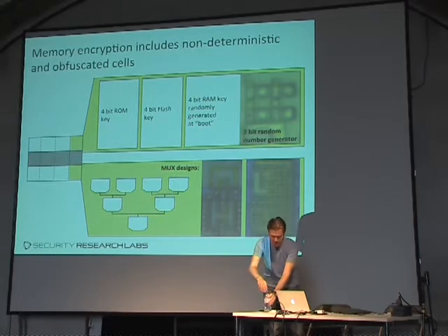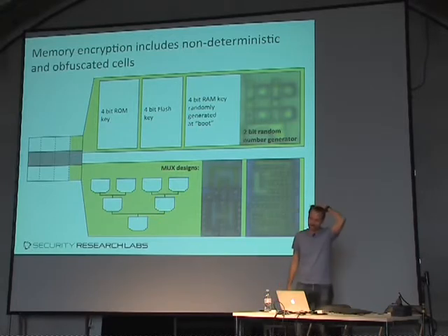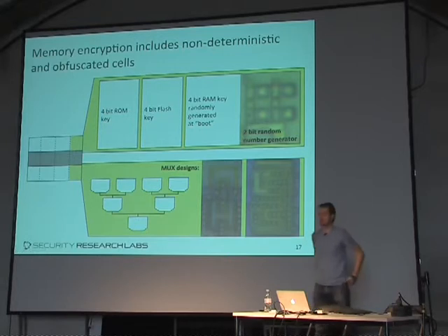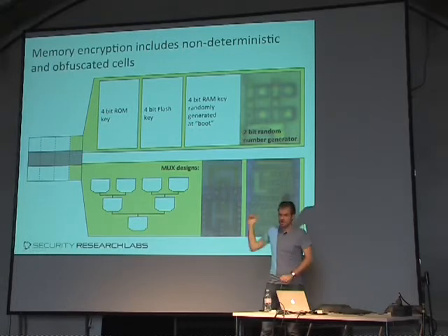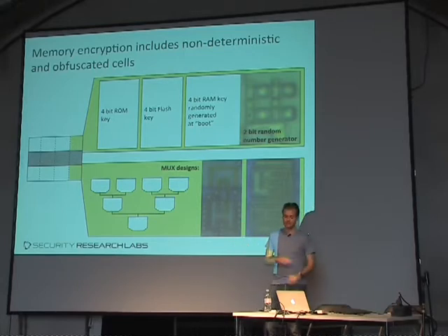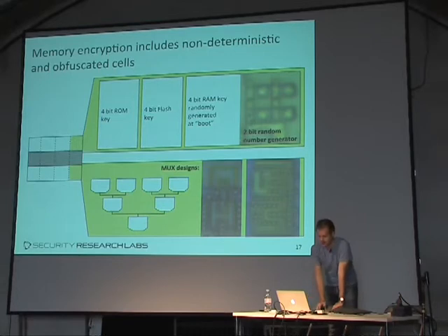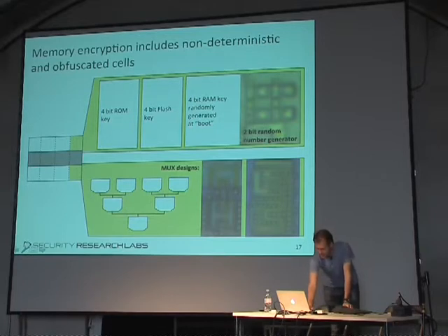So the last thing to point out about this encryption function, as I've actually mentioned before, is that this chip goes way out of its way, and only for the encryption function, no other part of this chip, to obfuscate the gates. Usually when you look at logic, it's pretty easy to figure out what it does. But with these gates, that's not the case at all.